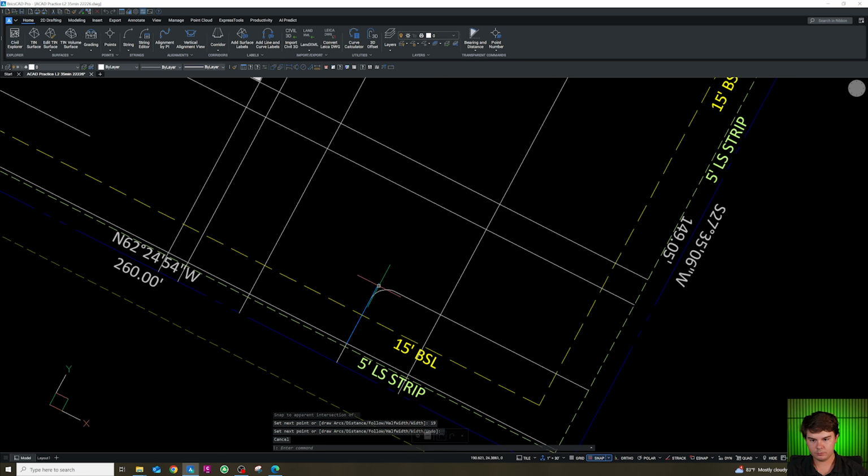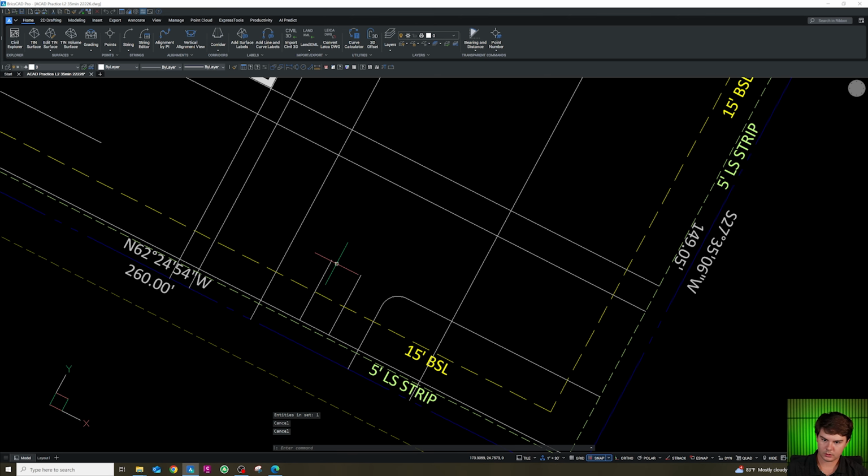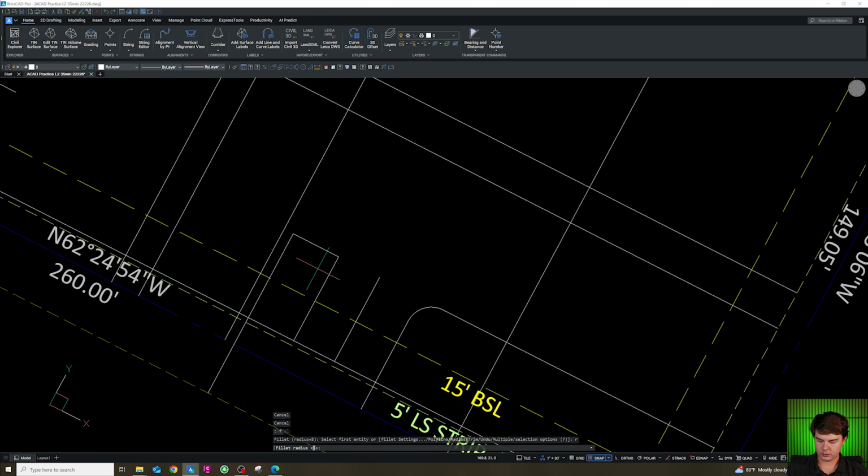19 feet deep. I'm going to offset this twice for our 2 spots. Go over. It looks like we have a 10-foot island between, so I'm going to go 10 feet. And then I'm going to go all the way down to our road where we're tying in. This has a radius of 2, and this has a radius of 8.